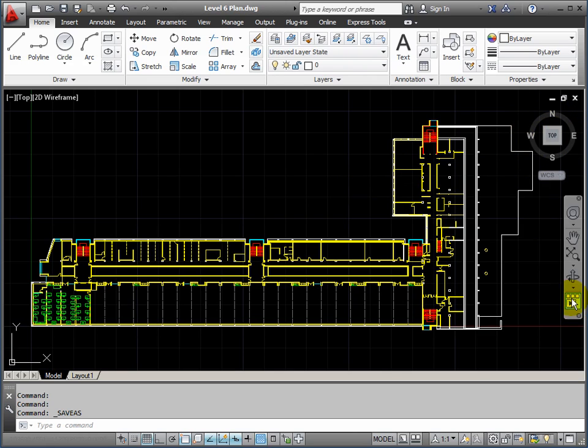Over this side there's a couple of utilities basically for navigating a drawing in 3D. These won't be of much use to a 2D drawing. Okay, they can't be fully switched off as far as I can see. They can be made smaller, but they can't be switched off. Okay, below that there's a line here. This is empty because it's expecting you to create more layouts. We have one model space, but you can have multiple layouts, and each one of these is looking at model space, and you set these up to be a view of a particular room, or it might be the whole floor, or it might be a detail of a stair, whatever. Each layout can be of different content.